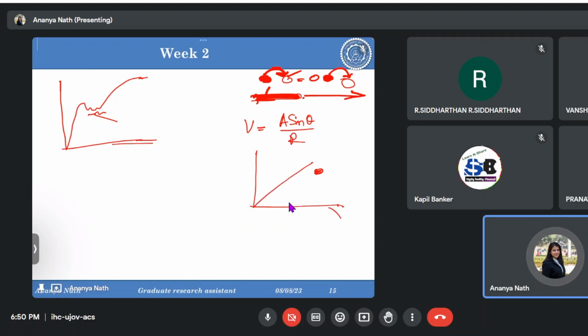This will be the dislocation movement, and that will be the theta angle from the slip plane, and the equation will be like this. U is the interaction energy between the dislocation and the solute atoms. So equipotential lines are defining the path for the dislocation or the solute atoms to move.